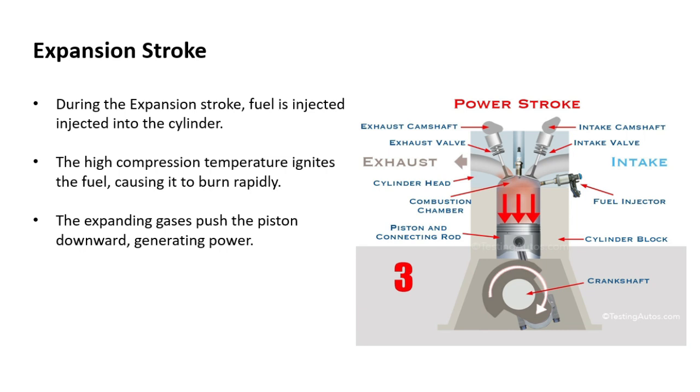Because of this explosion, there is a huge increase in pressure and temperature, and we are going to force that piston down. And as the piston travels down, it's gonna complete one full stroke. We are now at the bottom dead center again. We can see that on the crankshaft, and the stroke is referred to as a power stroke because that essentially is the stroke that is allowing us to extract the energy that we have got from combustion and turn it